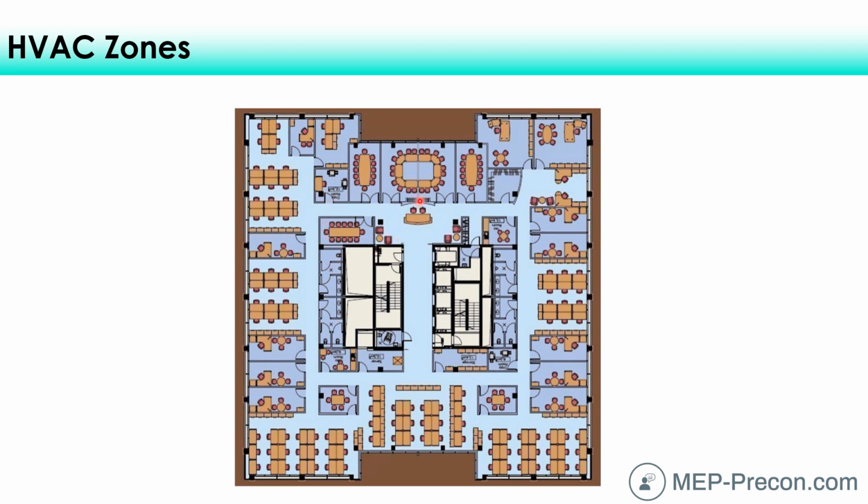And then conference rooms, here's some big conference rooms here. Would you have one big zone for all 3 of these conference rooms, or would you have 3? Well, ideally you'd have 3, but this is the art in trying to accomplish the balance between economy and comfort for an HVAC engineer. If you're going to be selling tenant improvements, this is a real art, and you want to make sure to communicate this with your customer as to how many zones you have, maybe even provide a zone map with your proposal to show your thought process of how you're going to zone it out.